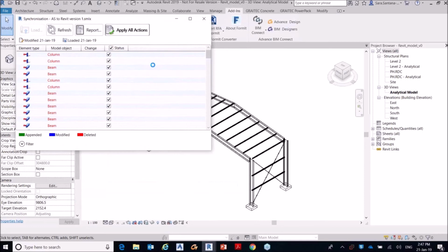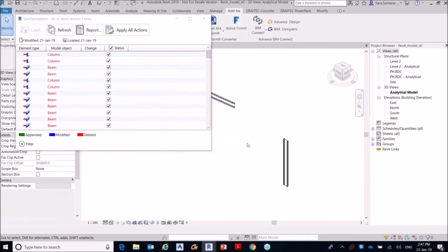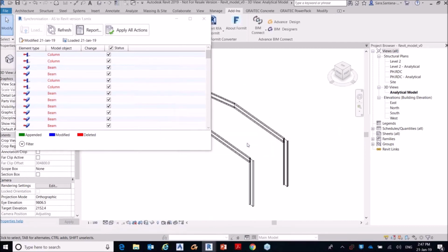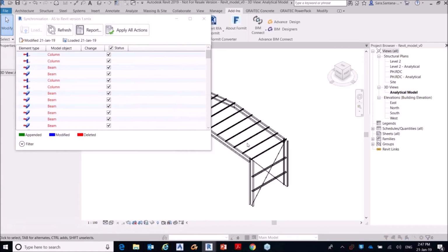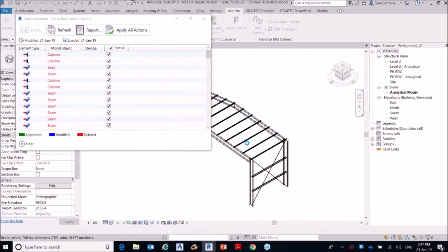In some cases, if it's a custom profile or an extrusion that exists in Advanced Steel and does not in Revit, you will be required to create the family in Revit, of course. In some odd cases, you might be required to do the process of mapping. However, it is not common with the UK profiles. Everything is pretty much seamless in terms of mapping the profiles.